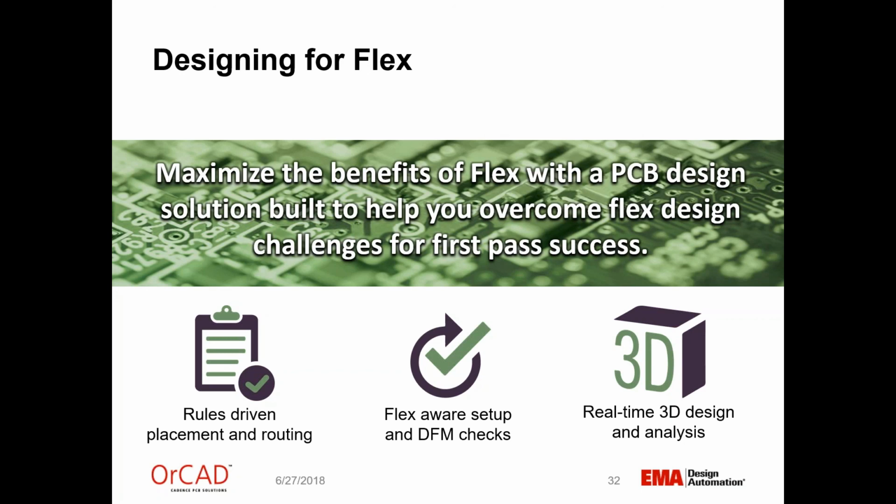Okay, we'll do a couple more questions here. How can I slide two rigid zones closer together? Do you shrink the length of the flex zone between rigid sections, or what? Yeah, you would have to modify your board outline if you wanted to have them closer together. You're talking about the length of the flex, not the radius of the flex.